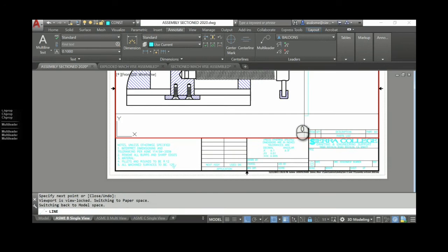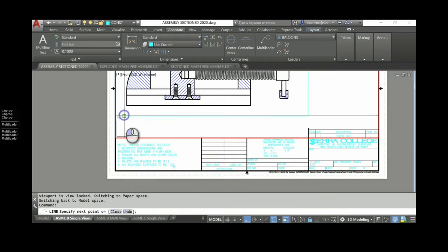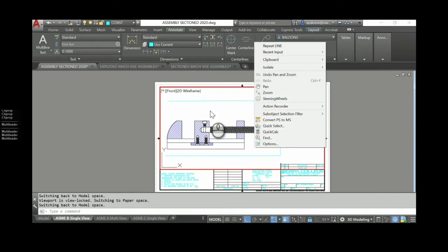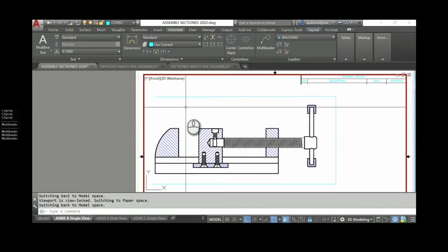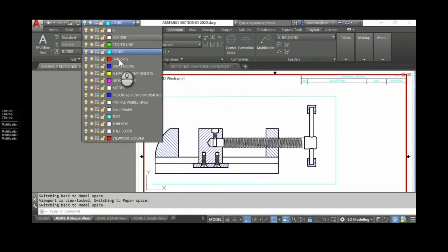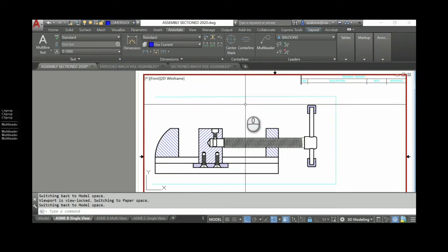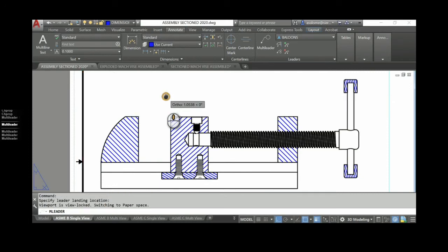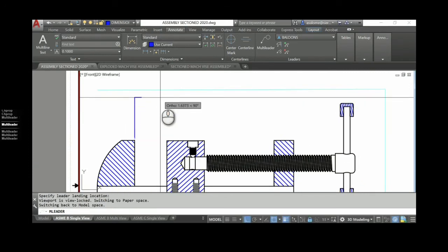Okay, they should line up nice and neat. So I like to put in a construction line here that won't print, and then I'm going to come in on my dimensions layer, and I'm going to use my multi-leader from my part. This is the only time I use a nearest to OSNAP.